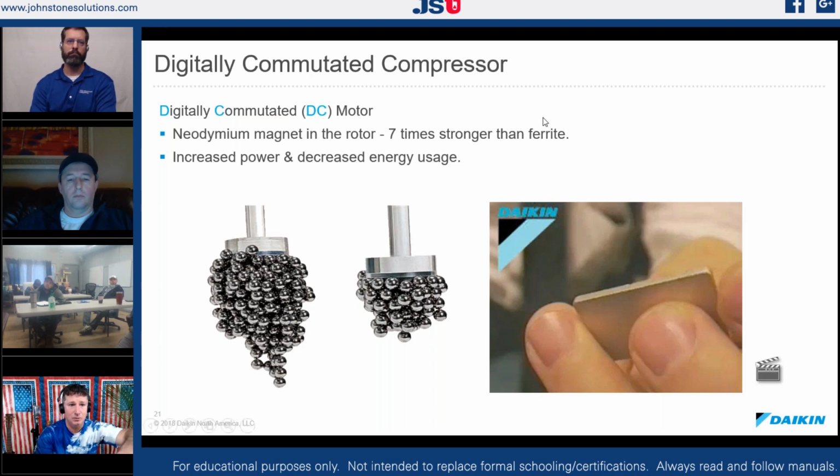Another thing that they did was they increased the efficiency of the motor by increasing the strength of the magnets. They went to neodymium magnets in the rotor, which are 7 times stronger than ferrite magnets. Increase the efficiency of the pump, and it increases the efficiency of the compressor. Increase the efficiency of the motor, and we also increase the efficiency of the compressor. The only other thing now that we can do to a compressor is change the motor, right?